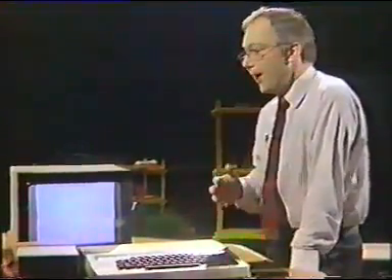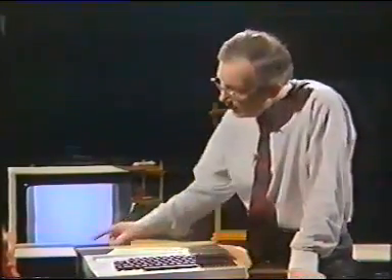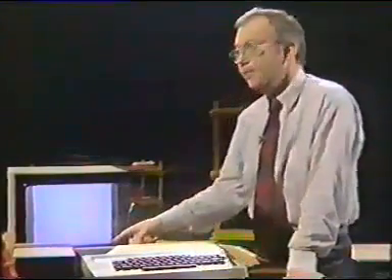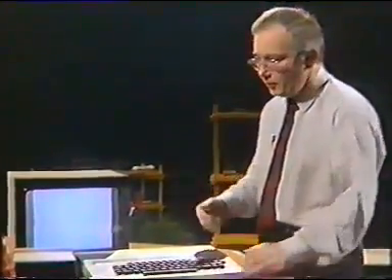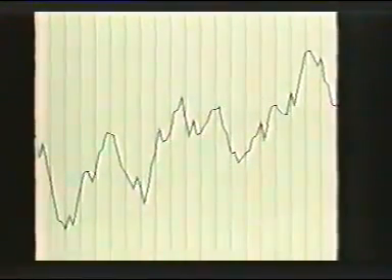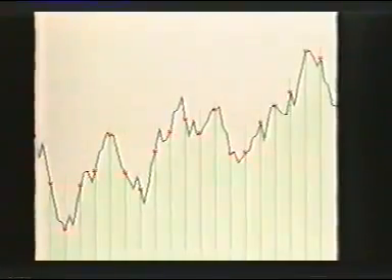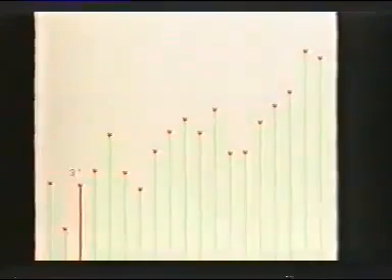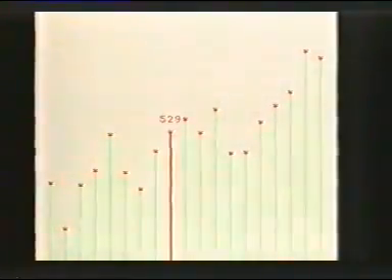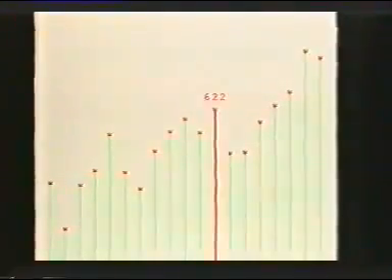The fundamental thing about analog quantities is that they vary. They don't just have ons and offs, they vary. And you can see the graph here, which represents the voltage of some signal against the time. And as you said, the microphone and the pressure pad are both producing voltages. Now, the computer samples those voltages at regular intervals, maybe every 50th of a second. And it then decides what the height of the signal is at those moments in time. And it reads those numbers in to the computer. That's an analog to digital conversion. We fed an analog signal in, and we've got a digital result to deal with.